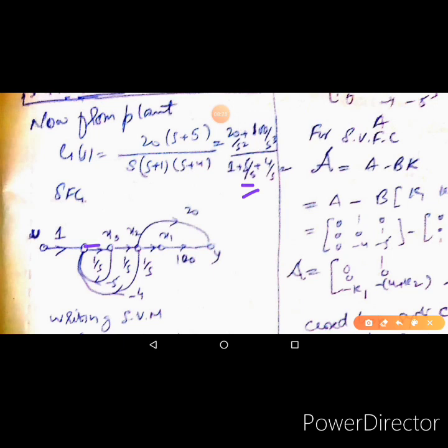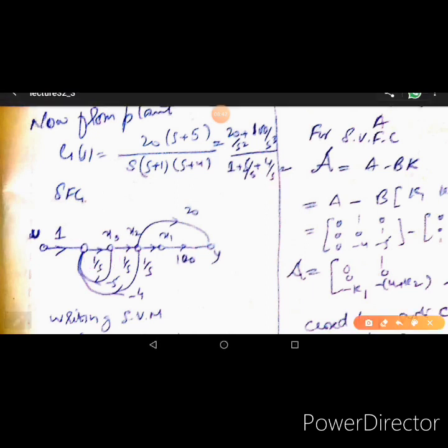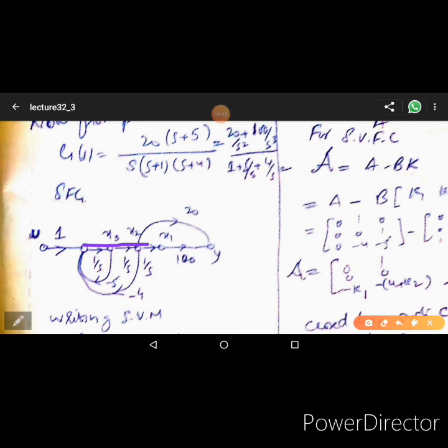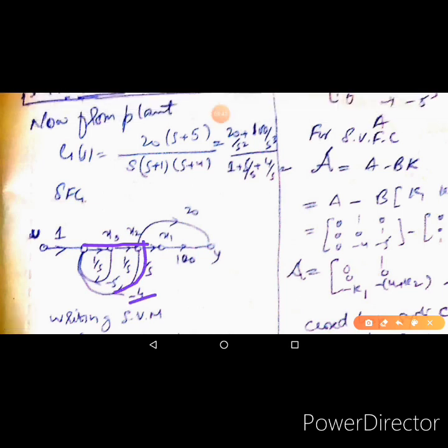That is what is happening. The signal gets integrated once, then multiplied with 5 and a negative feedback, therefore multiplied with minus 5, and goes to this node. Then as far as this term is concerned, the signal gets integrated twice passing through here and then multiplied with 4, then we have a negative feedback minus 4, and then it goes over here.